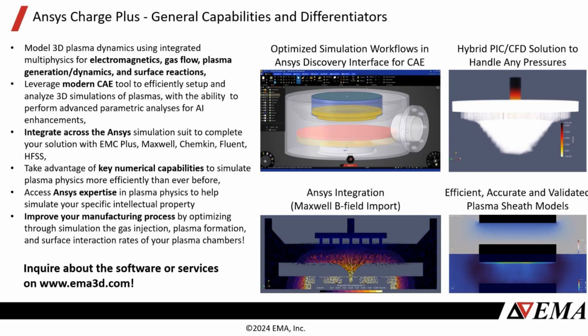How do you simulate etching or deposition once you have the 3D plasma distribution? Yeah, so that's a good question. On the bottom right here, you can see the electron density. We also have the proton density, and we monitor those near the surface through the sheath. That information is what you need to be able to solve for the proper surface reactions. We have an analytical surface reaction model, or you can get the surface reactions from Chemkin as well that you may have defined there.